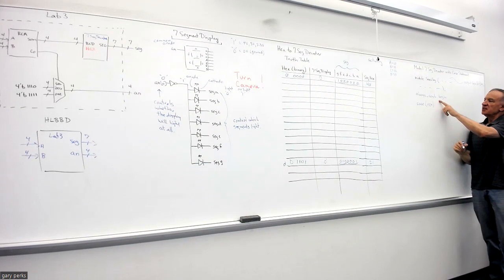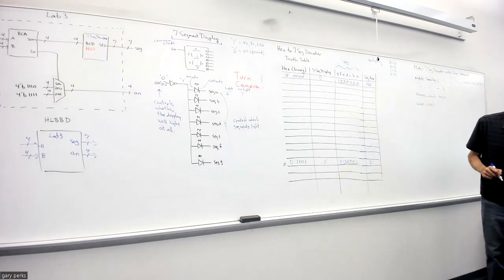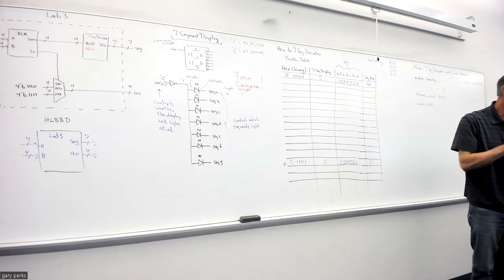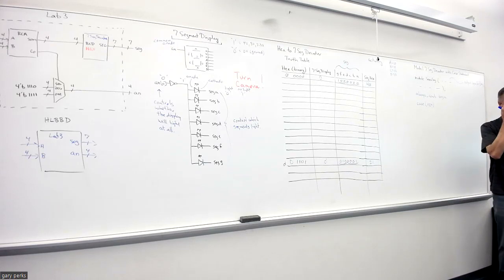Okay, now this begin is for the always home. So the case itself doesn't. I'm looking at my notes here because I always get the syntax wrong. It's a good thing I look, because a case statement doesn't have its own begin, like an if statement can have sometimes. We have multiple outputs like we showed last time. So with the case statement, the next thing that comes is just your options.